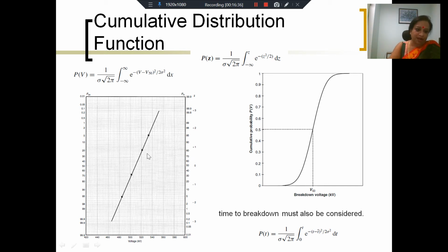Similarly, on this curve, on the left hand side is P_W, the withstand probability, and on this side we have the statistical withstand voltage, and here we have the statistical flashover voltage. As this voltage increases, the probability increases as a straight line, and then you have a value for which you have, let's say, 99.84 or whatever we said.